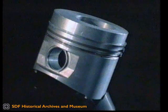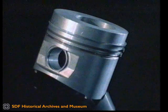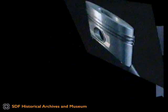In the new engines of the 1000 series, the highly accurate design of the profiles and the use of special materials have permitted a reduction in the number of piston rings from 4 to 3. The bottom sealing ring has a sharp-edged profile which guarantees a perfect oil seal during the initial operating hours. On later running in, the edge rounds off and fits perfectly against the walls. The reduction to 3 piston rings has permitted shorter, lighter weight pistons to be made, with advantages for the liveliness of the engine and rapid acceleration.